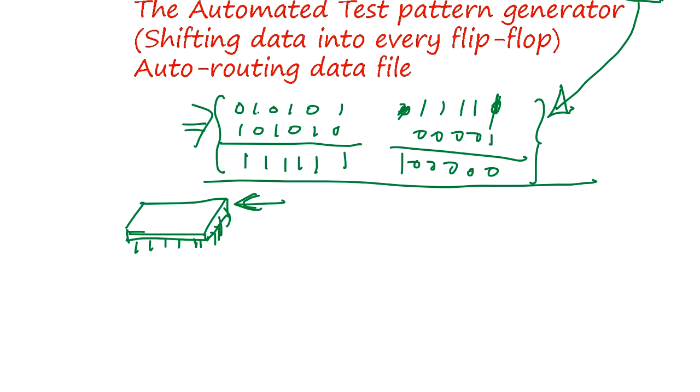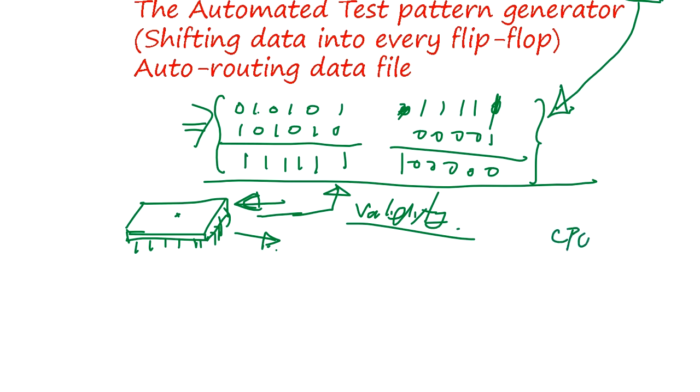For example, this validity test pattern has a limitation. You cannot test every case, right? So if there is one defect, one transistor not working, it may pass the entire validity test. Okay, but we cannot ship out this kind of chip, because in actual application, when you plug in the CPU, most likely it comes across very special cases that happen to use this transistor switching. Then it fails in the field. It's a field failure. We have to avoid this.